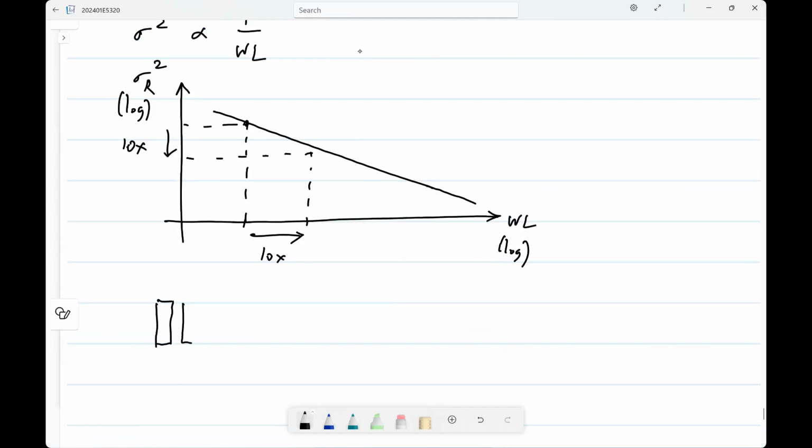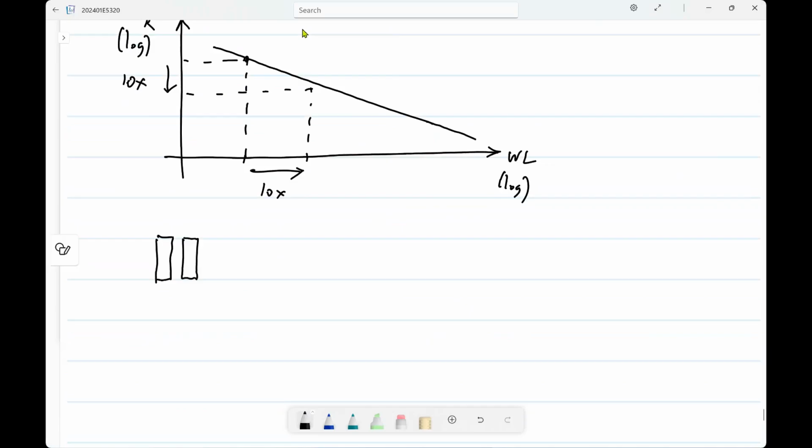So let's say you have two resistors close to each other, right next to each other, versus one resistor here, one somewhere far away. Now it turns out that the ones that are closer to each other match better. So there is some distance dependence. It's very hard to model by hand. We won't do that. If you have detailed process modeling, you will have that as well. So this has better matching and this has worse matching.